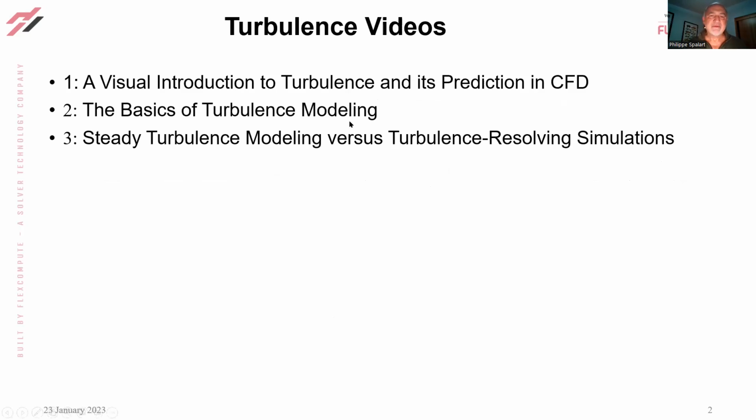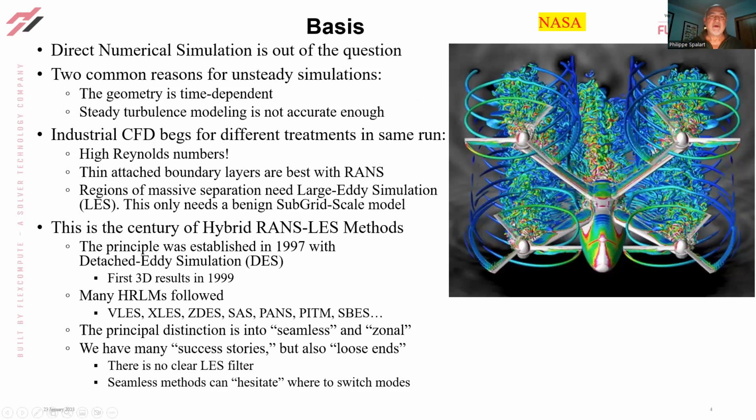For a little bit of perspective, the basics of turbulence modeling we've been working at for about 100 years, and turbulence-resolving simulations more like 15. Okay, so the basis of doing turbulence resolving instead of just straight steady turbulence modeling. Well, first of all, direct simulation that you saw a few of is completely out of the question based on cost.